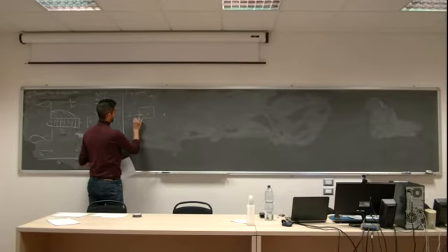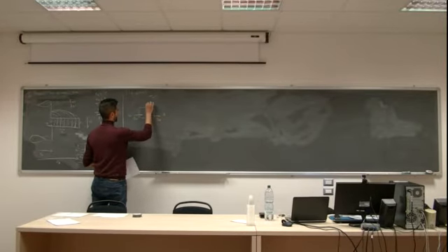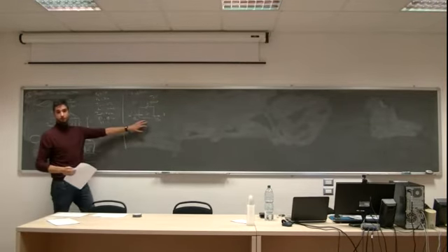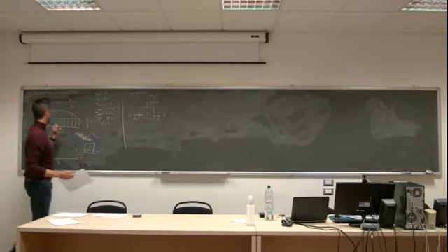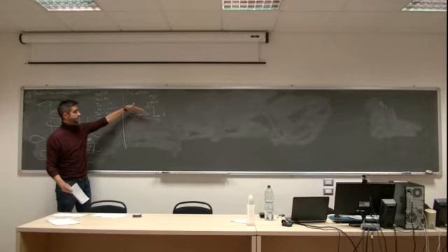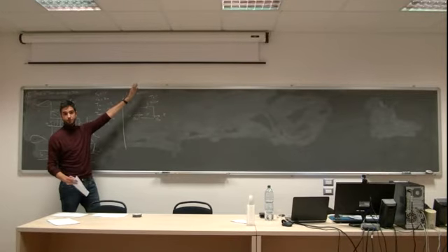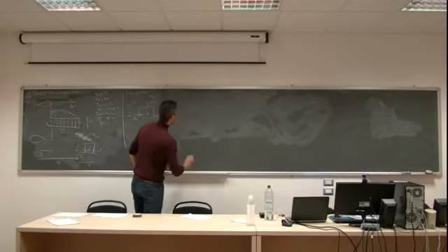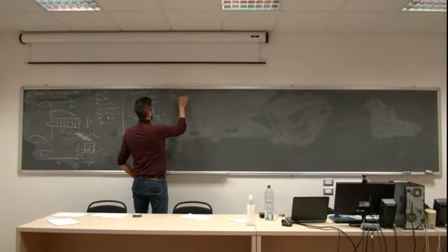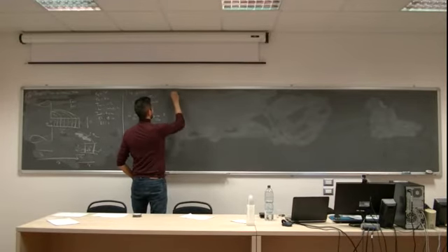So we have, do you agree with me? Each of the nodes between 1 and 6 has a conduction coming from the west, a conduction going to the east, and is dissipating by convection. Right? Okay. How can I compute Q conduction west? Oh, Q west, I say.